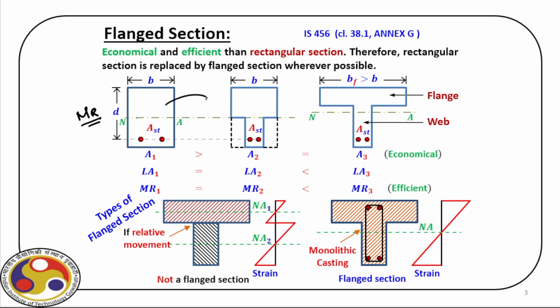And then from this what we get is a new cross section where we have the upper part of the neutral axis remain as it is. The only modification is that we have a small portion of the concrete in the tension zone that is actually holding this steel. Of course, we have to satisfy the requirement of clear cover or effective cover and the distance between bars. That we are not for the time being worried of.